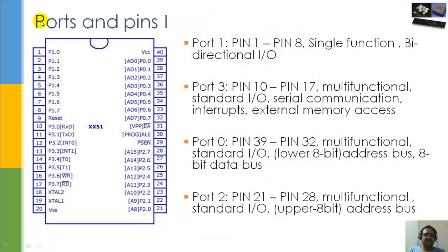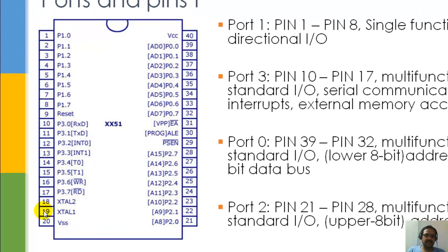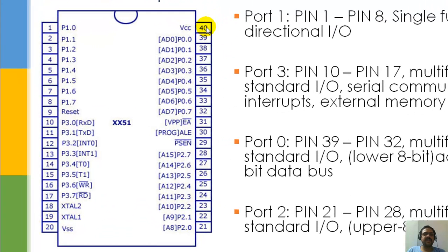But this particular diagram is the structural diagram that depicts how 8051 will look. This is the notch which you see in any chip that you buy. The left hand side of the notch is pin 1. Basically, it's a 40 pin IC. We call this kind of construction or structure a dual inline package, or DIP package. What do we mean by dual inline package?